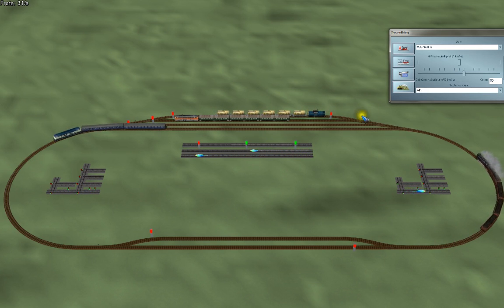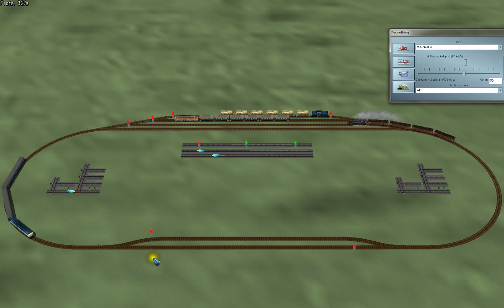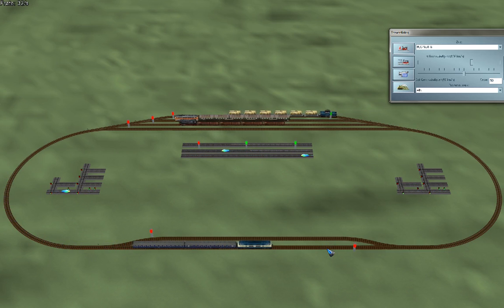Train north wants to go to south, but the track is occupied, so it is neatly waiting. And we will see if this train that comes in is going to select track 1. That is the only track where no train is on. If it is over here, it will trigger the request sensor, but there was a 10-second delay, so let's count down. 9, 8, 7, 6, 5, 4, 3, 2, 1. I think right now the car should go. Yes, there it goes. It selected track 1, which is perfect.